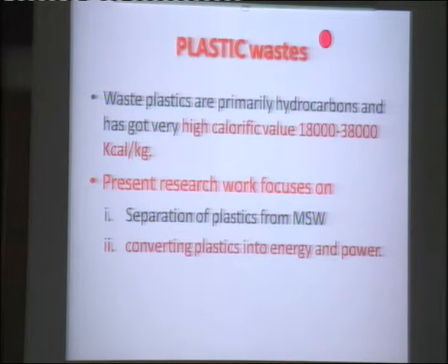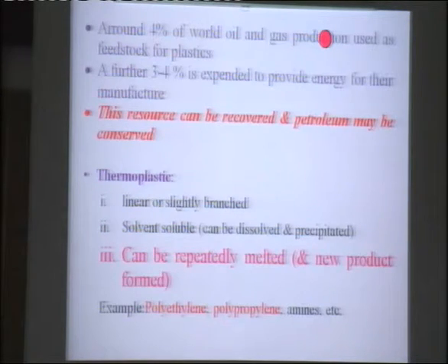In the Indian context, MSW, municipal solid waste, contains more than 40% inerts, organic matter 30 to 60%, plastics less than 1%, paper 3 to 7%, and calorific value 800 to 1100 kilocalories per kg. Under this condition, it cannot be burned, so that plant is not running.